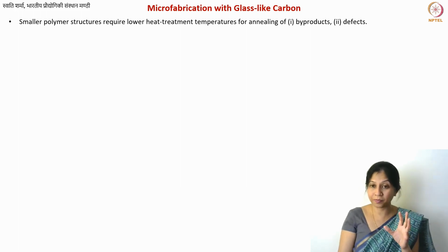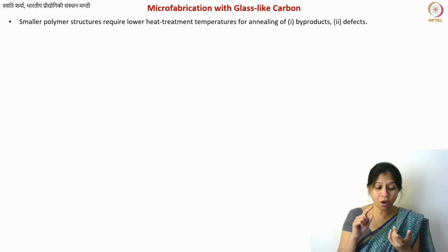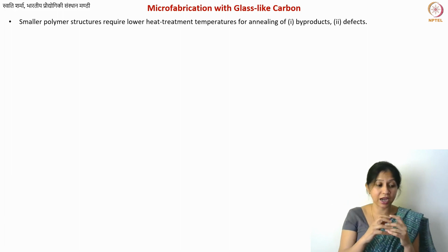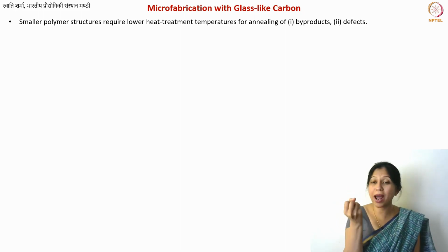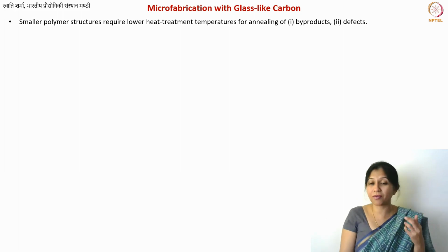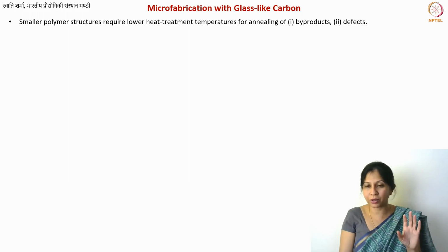It is not possible if you have strongly curved carbon structures, or if some of these strongly curved structures completely convert into fullerene-like structures. They become completely closed, so they are spherical or cage-like structures, as we call them. Once you have a defect or a bubble or a void trapped inside these curved carbons, it will be very difficult for it to break that structure and get out of the material. But there are also several voids which can anneal out. What we need to do is provide certain energy in the form of heat.